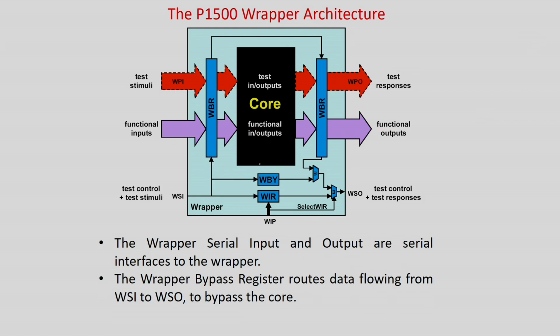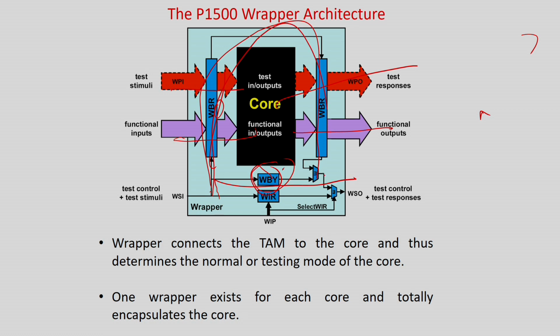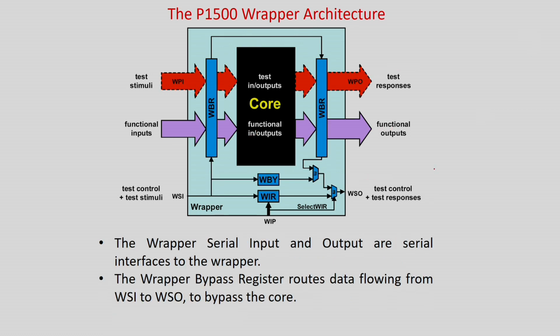So it means if you have to scan through all the chips, all the cores in the die, it may take a long time to do that, and it is not required at every point of time, because maybe only 2 cores I am interested in. So some of the cores I will directly bypass. Instead of going in the roundabout direction, I will directly pass this chip. As I told you, not by this direction, I can go by this.